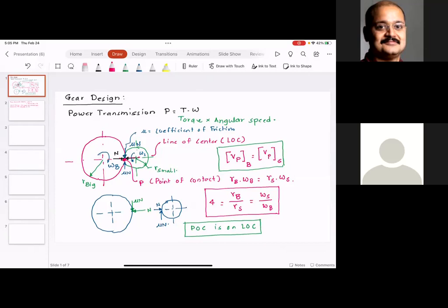So coming back to the gear transmission that we are talking about, I want positive power transmission. Do you agree with me? Friction wheels are not positive power transmission. Slipping is possible. So how would I turn this non-positive power transmission into a positive power transmission? Cut teeth.